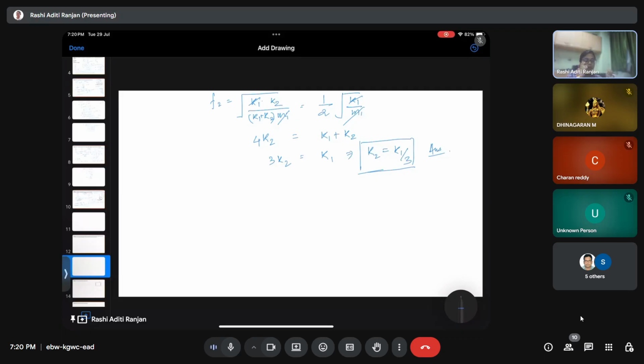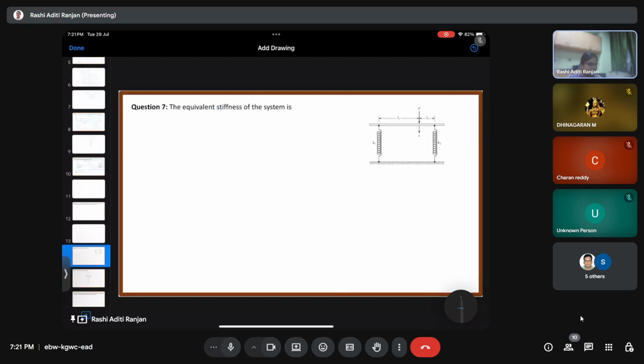So then what will I do? I will introduce another spring into my system that will make the natural frequency half. In that case, I have no problem now, because even if I give it 20 hertz, it is twice the resonance condition, right? So we use these kinds of things when we want to tune the frequency of a system in order to avoid resonance conditions.